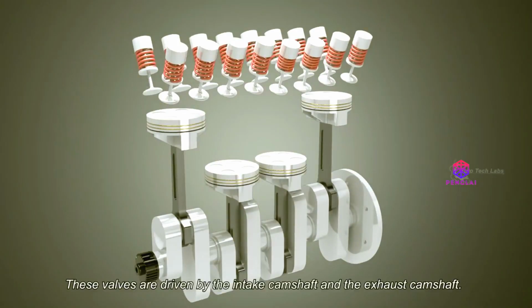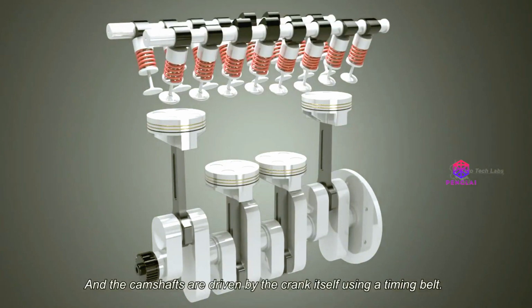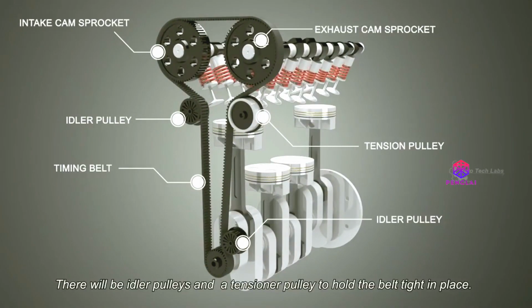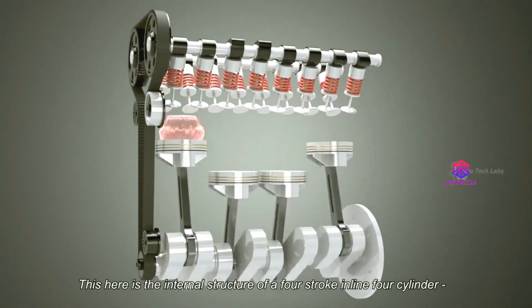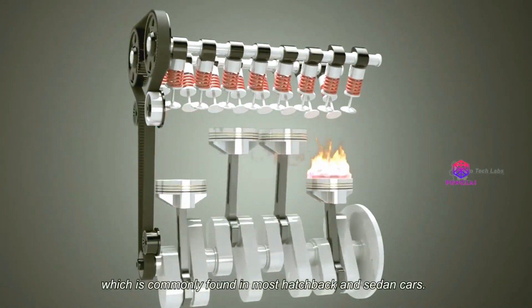These valves are driven by the intake camshaft and the exhaust camshaft, and the camshafts are driven by the crank itself, using a timing belt. There will be idler pulleys and a tensioner pulley to hold the belt tight in place. This here is the internal structure of a 4-stroke, inline 4-cylinder, DOHC engine, which is commonly found in most hatchback